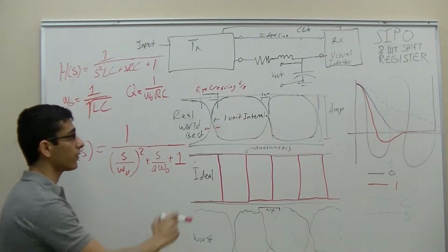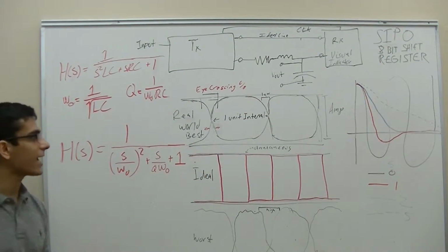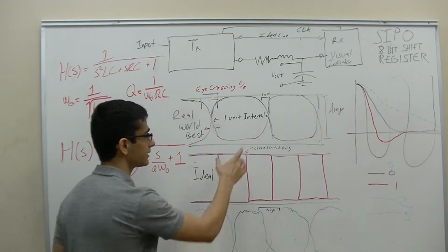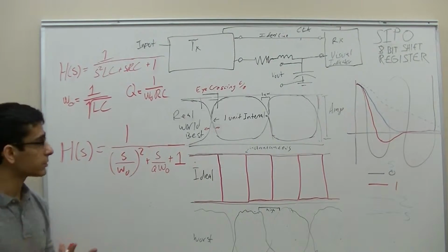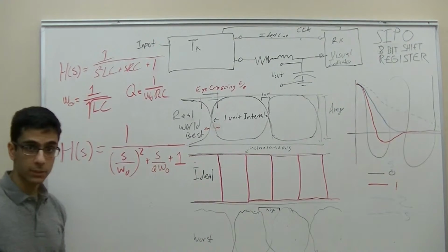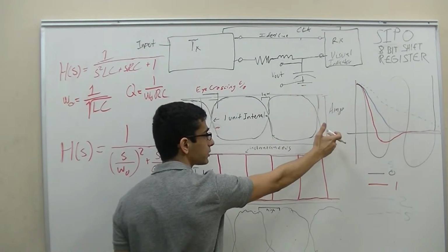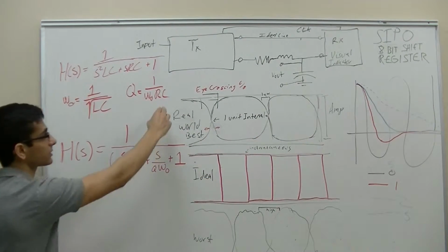That way, on the oscope, you'll see an eye diagram that will look something like this, because it resembles an eye. So you can think about it that instead of measuring across an interval of time, it'll be 1 unit interval in which bits are measured and triggered over time based on the clock signal. Over here you have the amplitude, which you can think of as 1 or a 0, as it triggers from the top to the bottom.